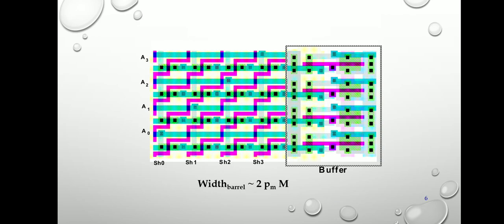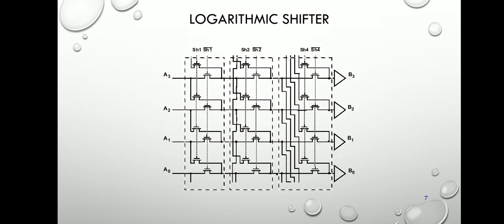In this barrel shifter, data can be shifted by a specific number of bits without the use of any sequential logic, that is, only pure combinational logic. We can change the operation into the binary operation. It can be used to implement binary operations such as logical shift left in limited amounts, and the way to build this barrel shifter is to chain a sequence of multiplexers, where the output of one multiplexer is connected to the input of the next multiplexer.